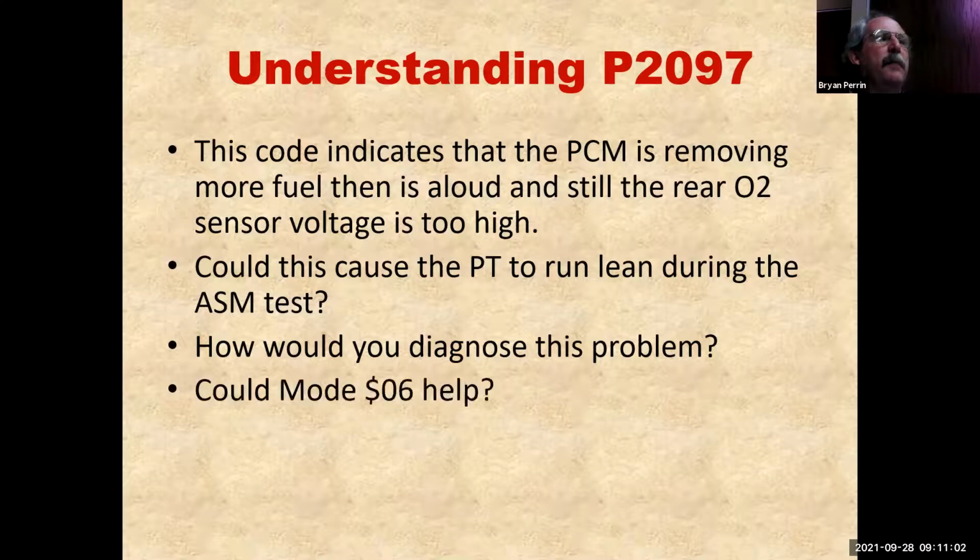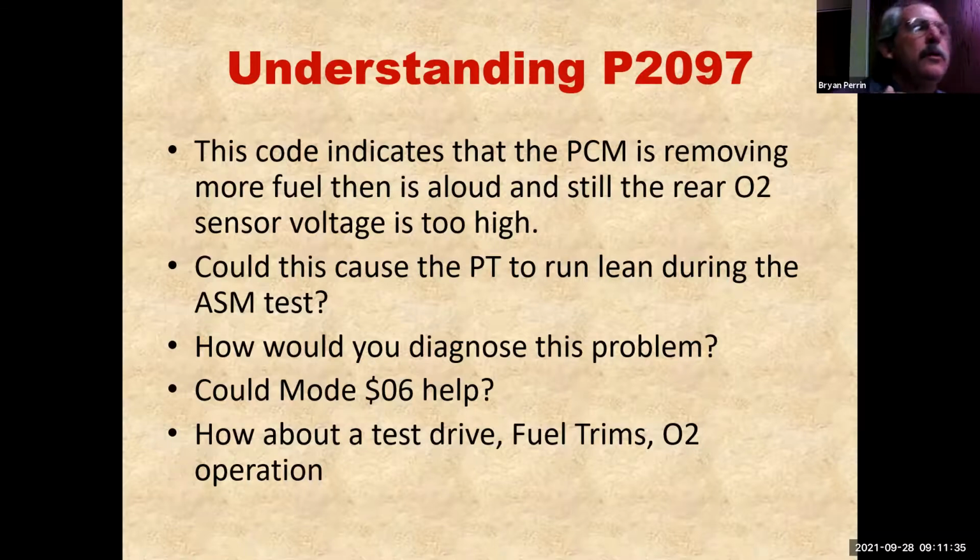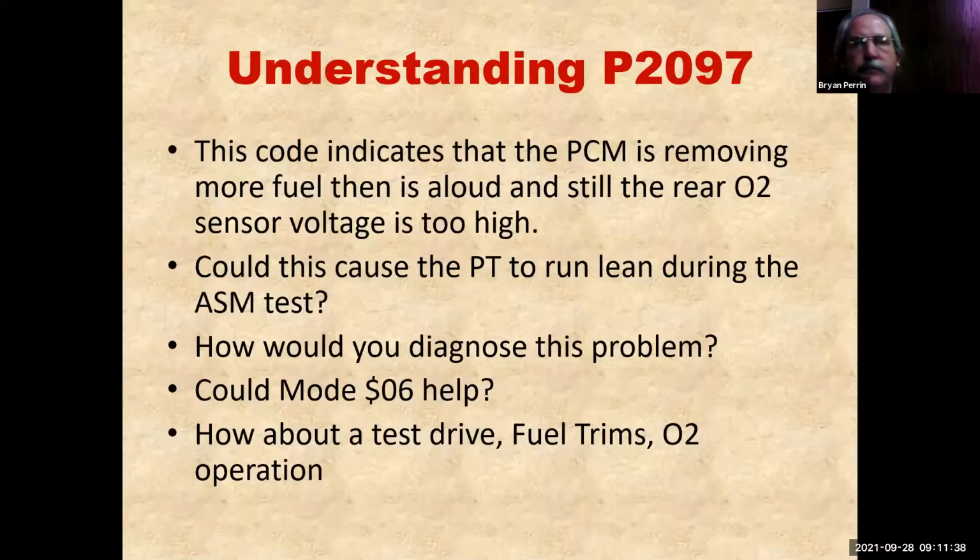So how would I diagnose the problem? Again, I'm kind of spitballing here. Could mode 6 help? Maybe. How about test drive, fuel trims, O2 sensor operations, right? So what am I doing? I'm looking through my toolbox here. I'm looking through my list of resources. What do I have that might give me an answer to whether I'm on the right track or not? No different than looking through your toolbox for the right size wrench or the right size screwdriver. I'm looking through my toolbox on a vehicle, going, which tools do I have? What scan tool functions do I have? What other things can I do to help prove whether I'm correct or not?